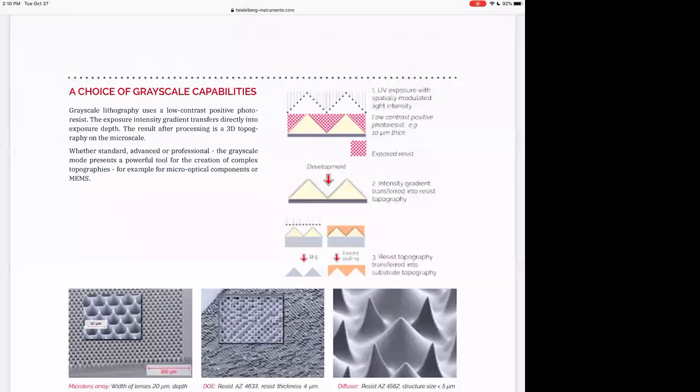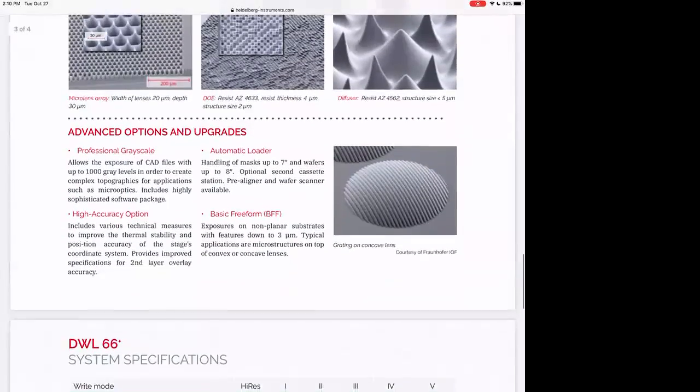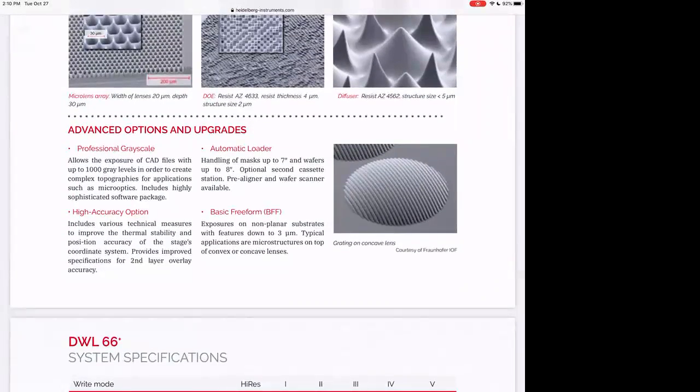And so you can get these sort of slope structures, you can get intensity gradients that are transferred to a single layer, but this is not a vat type process. This is more in the realm of 2D or 2.5D. So you could compare this to just lithography, like UV lithography of Pentium chips or something like that.